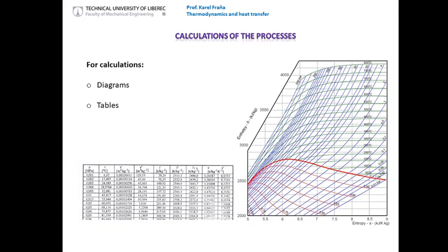For instance, here below, the tables indicate just a specific pressure and specific temperature, which are practically the same for the saturated mixture. That means you define only the pressure or only the temperature because they are not independent of each other. And you can calculate the volume with one line and two lines. You have already heard from me that one line indicates a saturated liquid and two lines a saturated gas, and you can use them now for the calculation. In the table, you will find the same for the enthalpy and for the entropy.